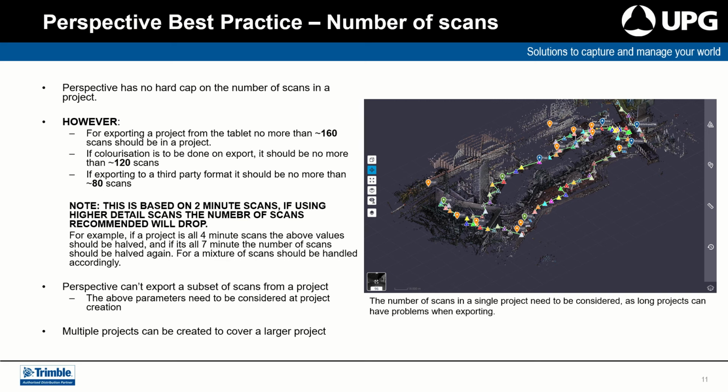And be aware that the colorization and refinement step, and also the exporting to a third-party format out of Trimble Perspective, can take time depending upon the number of scans. So there are cases where it is recommended that different projects are used as opposed to doing one single project with a lot of scans, to help speed up these processes.